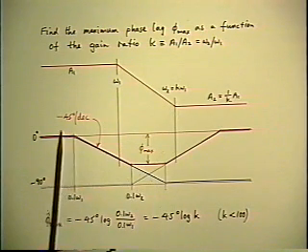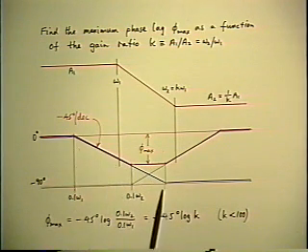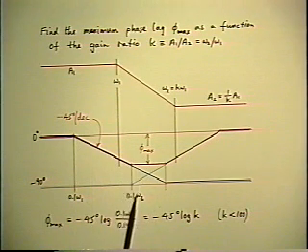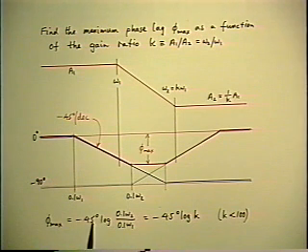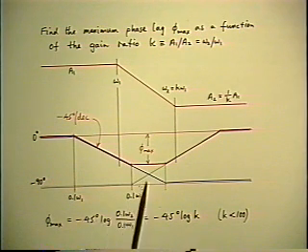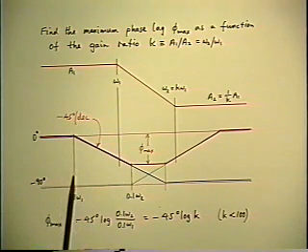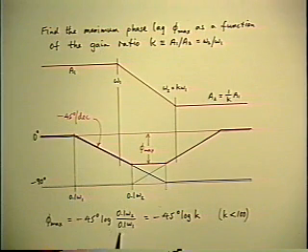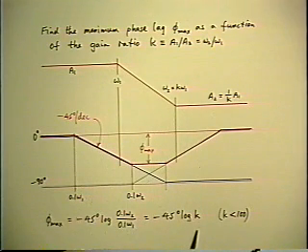So remembering that this is a semi-log scale, minus 45 degrees per decade of frequency, evaluating the phase lag at the frequency 0.1 omega 2 is simply the slope, minus 45 degrees, times the log of the ratio of 1/10 of the zero to 1/10 of the pole. And the 0.1s cancel out, and the ratio of the corner frequencies is the parameter k, which is the same as the gain ratio that we're trying to throw away.